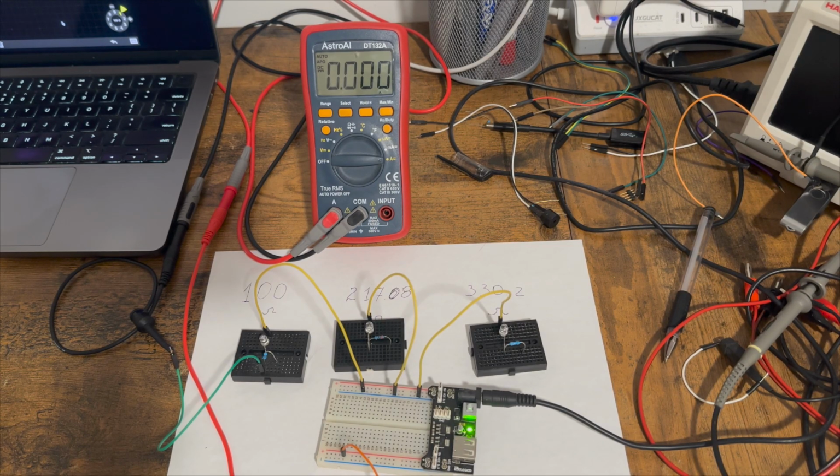And in order for you to figure out what is the resistance that you need to use, you need to find out what is going to be the voltage forward. Usually it's different for red, blue, and white LEDs. So you're going to have to figure that out and use Ohm's Law to calculate how much resistance you need. And that's pretty much it.